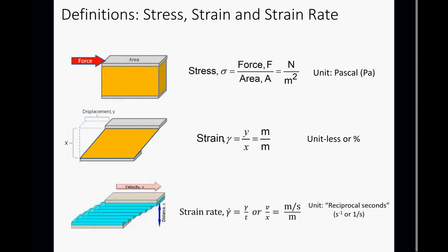There are three metrics, or three definitions, that we need to define here, really: shear stress, shear strain, and strain rate, or shear rate. Okay. So whenever we either handle a material, or we assess a material, or a rheometer measures a material, it's controlling one of these and it's measuring another.